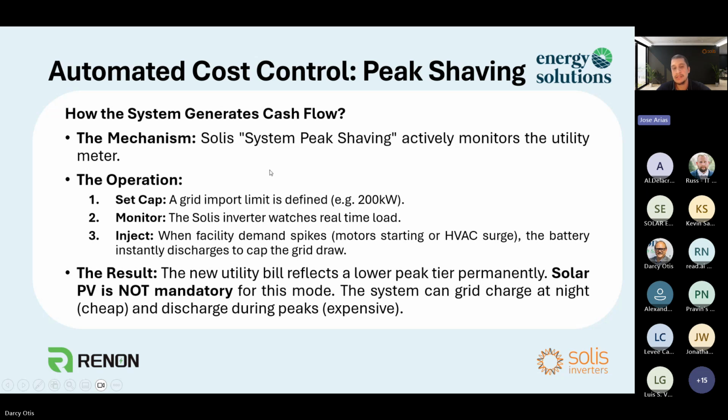It can be started small, maybe without PV at the beginning, and later on, in a later stage, add a PV array connected to the PV hybrid inverter from Solis. And this combination will give you great results regarding the economic feasibility of this investment. It can be charging from the grid when it's a cheap electricity cost, and discharging when it makes more sense, when you don't have PV at the beginning.